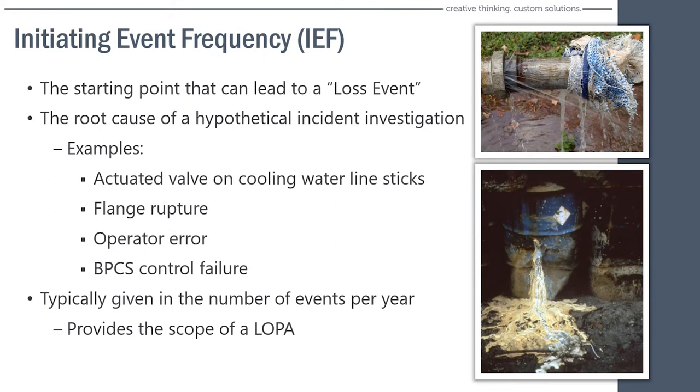So now you're talking about, okay, what is our initiating event frequency, is it 1 in 1,000? Yes, that's kind of what it is. We would have 1 failure in 1,000. Maybe from your experience, you're finding that that initiating event frequency is much higher than that. Maybe you have overfilled that tank and you have had a spill in the dike. On the other hand, maybe you've been running that process for 20 years and the operators have never overfilled that tank. Those are numbers you have to have in the back of your mind when doing this LOPA to figure out the typical initiating event frequency. But for simple purposes, let's say it's 1,000 times a year. So, one failure in 1,000 would be 1 in 1,000.